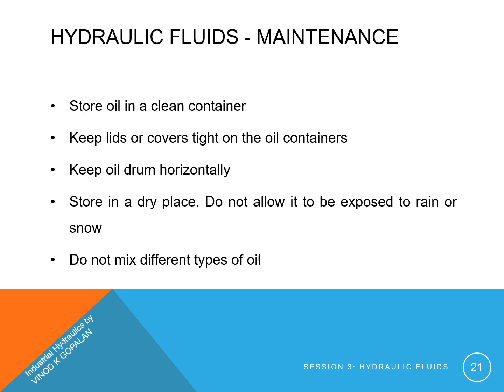Maintenance of hydraulic fluids. In the beginning of the session, we have seen that hydraulic fluid influences the performance, maintenance costs, and service life of the hydraulic system. Therefore, it is very important to maintain the oil properly. Store oil in a clean container. Keep lids or covers tight on the oil containers.